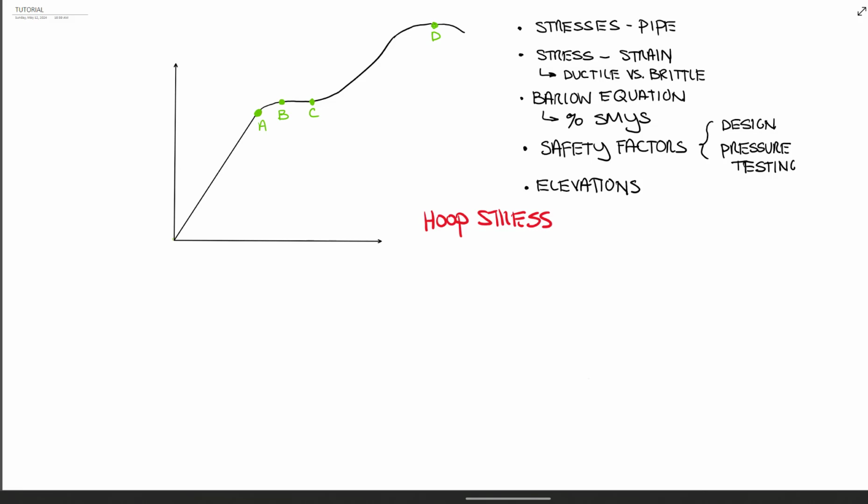Now, axial stress is actually aggravated by hoop stress. So as the pipe expands, axial stress is basically longitudinal stress, so in the direction of the pipe body, and it can be aggravated by maybe backfill. So say you have a straight piece of pipe and then you backfill and it kind of bananas it a little bit. So not only when that thing's in operation do you have stress going up and down the body, but now that you backfilled and bananaed it, on the outer fiber of the body you've just compounded the problem.